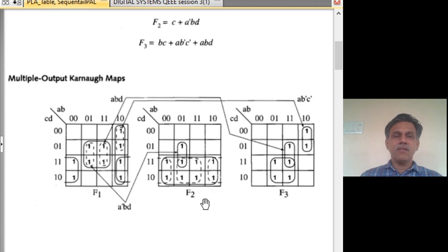And when we generate it in the programmable logic array, the number of literals in each product term is not of concern to us, because all literals are already available, and the cross points or mask gates are also available. We are only going to remove which is not needed.